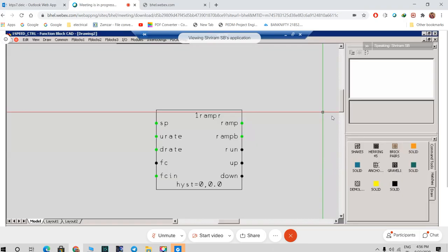And there is also a fault for old data and derived fault. Old data means that whatever data is there, it has got frozen. And this derived fault is like, suppose you are having a calculation, and one of your analog inputs is in fault because of some wire break or something, so that input will be in external fault. And suppose you are having a calculation like input 1 plus input 2, so now your output will see that one of your inputs is in external fault, so your output will go to derived fault. So it is a derivation of your fault. Whenever a calculation is happening on a fault, that will be a derived fault.